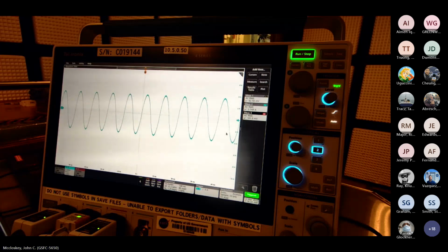That means our source impedance is probably a little bit higher. It just means our source impedance isn't exactly half an ohm. And that wire is adding some inductance. That's why I said if you really wanted to do this properly, you'd place a very short piece of wire between those terminals and clamp your current probe around it. We'd probably be getting a little bit more current here, but this is sufficient to illustrate the point. So now let's go to a kilohertz. Our level was minus 16.7.